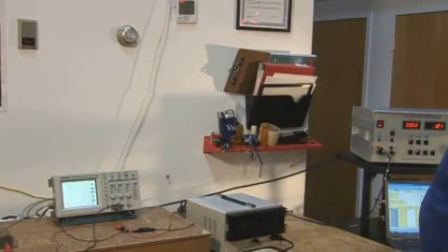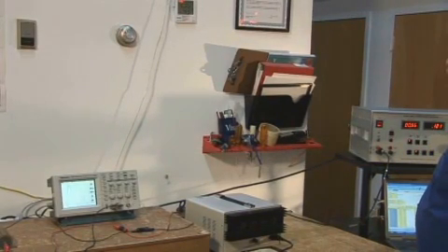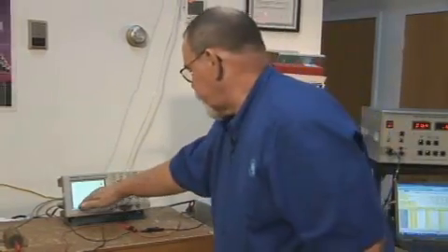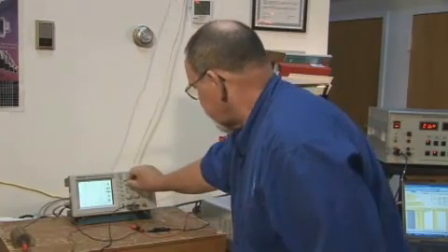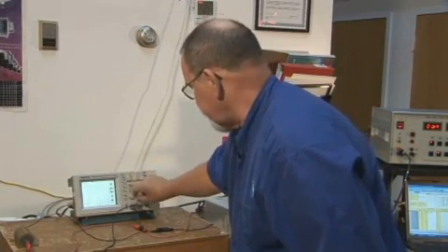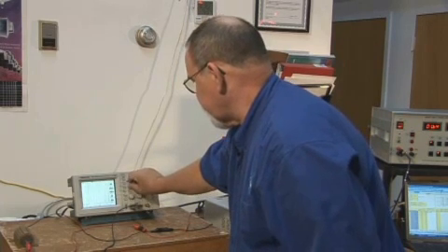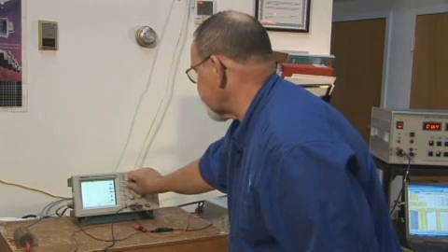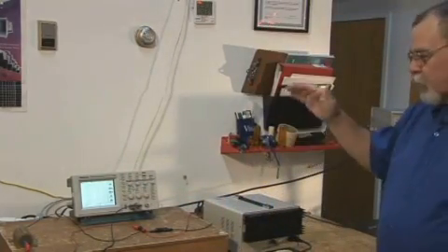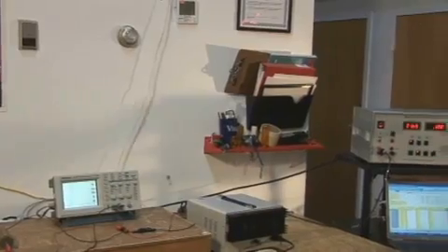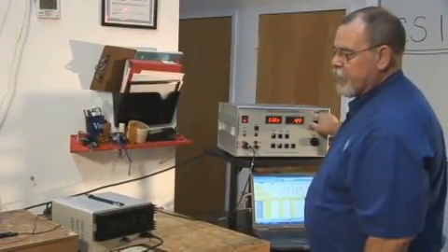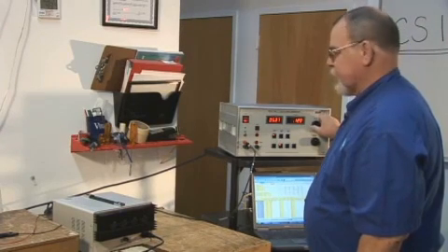I increase the level until I get the excursions to be 17 volts, 17.8 peak to peak. We're on 50 volts per division, so I'm going to actually position the waveform to where it's not very visible to me so I can get better resolution. I'm at 20 volts per division. So 17.8 volts would be approximately 1 division peak-to-peak excursion. So I keep adjusting this till I see that waveform varying by that amount.